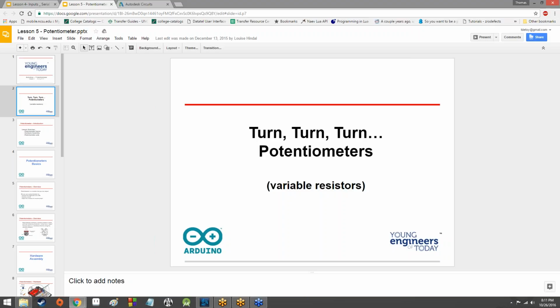The hilarious thing was, since an LDR reads an entire spectrum of light, and we needed red, the way we fixed that was we put some red cellophane over the LDR. Part of what makes something red, like red cellophane, is it only lets red light through.